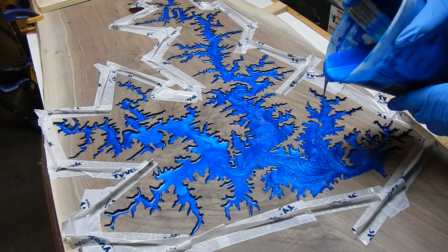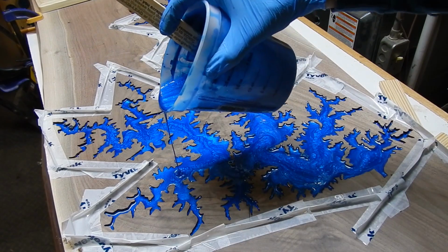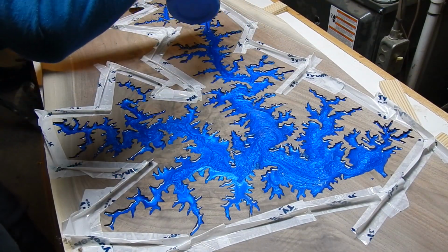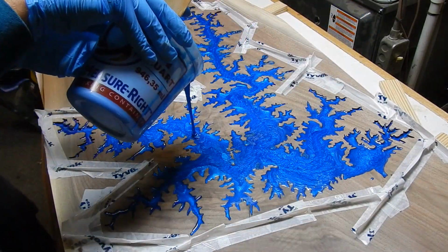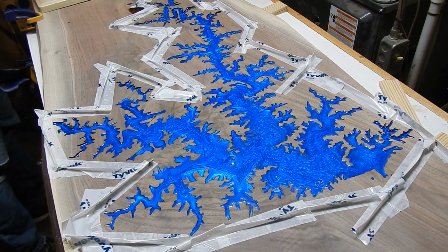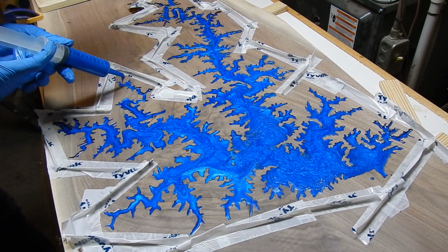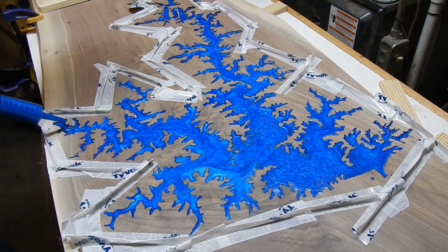With the lake totally filled into its borders, it's time to go back and pour in more epoxy. One of the things I'm sure you noticed that I haven't commented on is I use Tyvek tape to basically create a moat around the lake. At this point, I'm starting to fill the lake in and overfill it at certain points. I didn't feel like sanding as much as I could have, and I didn't want it to mess up my shop. So the Tyvek tape is a great way of containing the mess and allowing me to overfill.